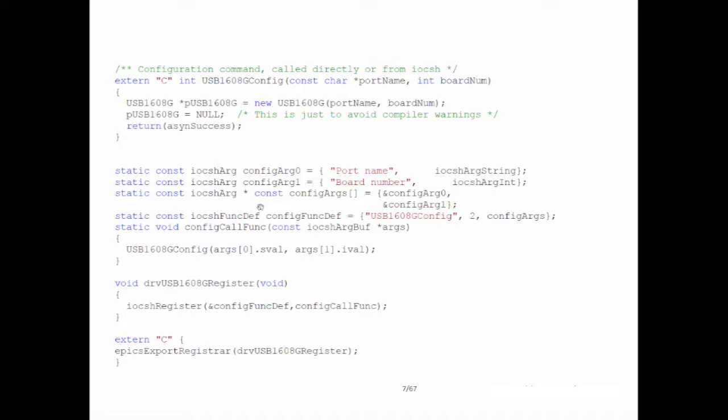So there may be parameters that really only apply to address 0, the firmware version, for example, but we're duplicating that parameter for each subaddress. For the first and second and third analog inputs, they all have a parameter for the firmware, even though they probably don't need it, because that's all the same. But it's simpler that way. It's just n copies of a single list.